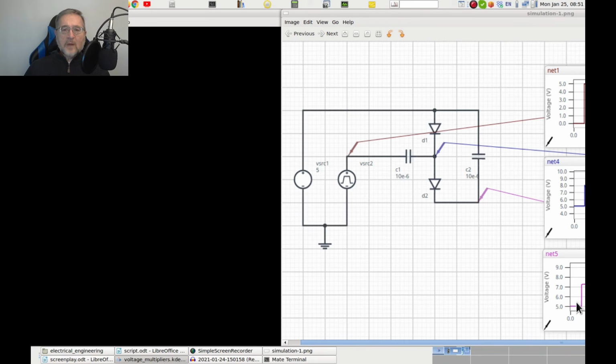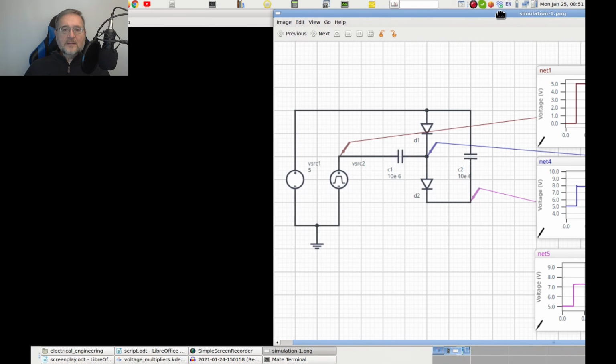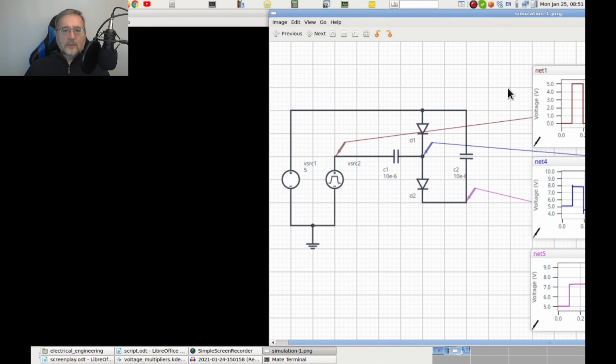Next, the square wave changes to 5 volts, and at the point in between D1 and D2, the voltage, which is the sum of the one of the generator and the one of C1, spikes up. This turns off D1, since now the voltage of the cathode is higher than the one at the anode. D2 instead will remain on, and a current will flow from the generator and C1 into C2 across D2. As a result, half of the charge of C1 will transfer to C2.